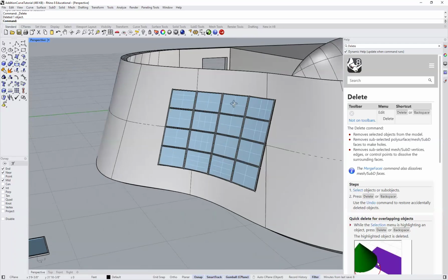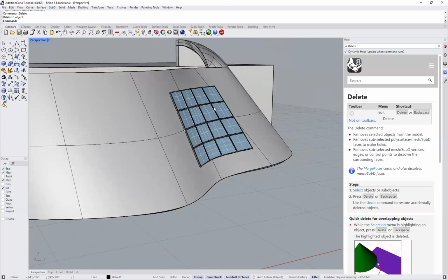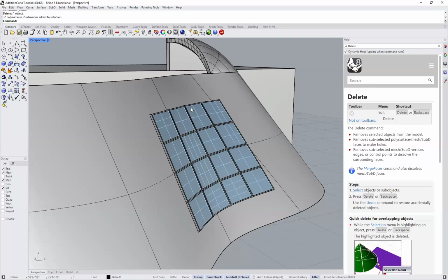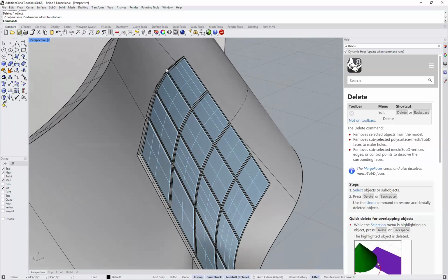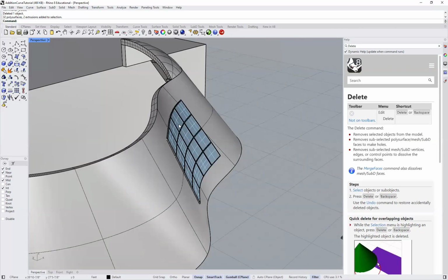So we don't really have to worry too much about it fully functioning. Now, if we were to take this into doing construction drawings from this, then what we would do is we would cut a section through it and we would adjust the discrepancy in that curvature in the 2D drawing, right? We do a make 2D, and then we just kind of adjust the line work as needed to show how it would actually be installed.